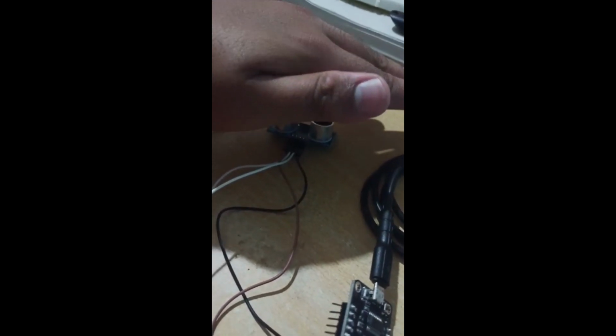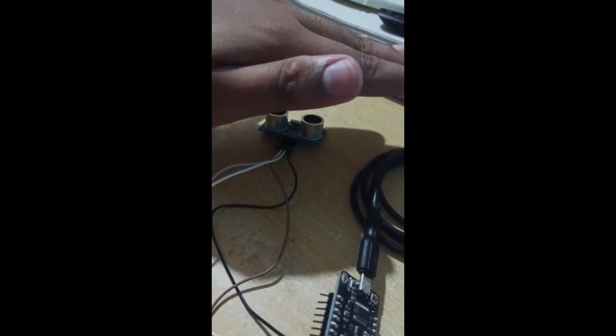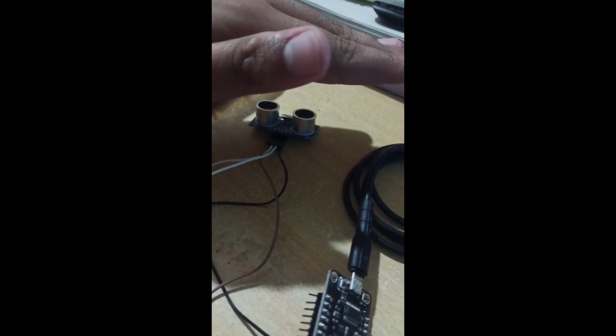It runs slowly now because directly opening ThingSpeak takes time. Here you can see the default distance, 62 centimeters and so on. Now I am keeping my hand here. For the next 15 seconds I will keep it like this, so that the distance will be reduced. We will wait for 15 seconds. Yes, here you can see 4.36 centimeters came.